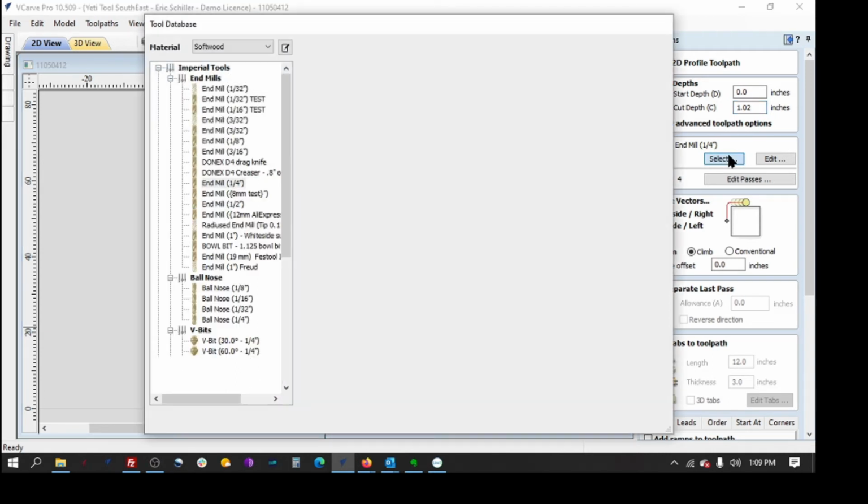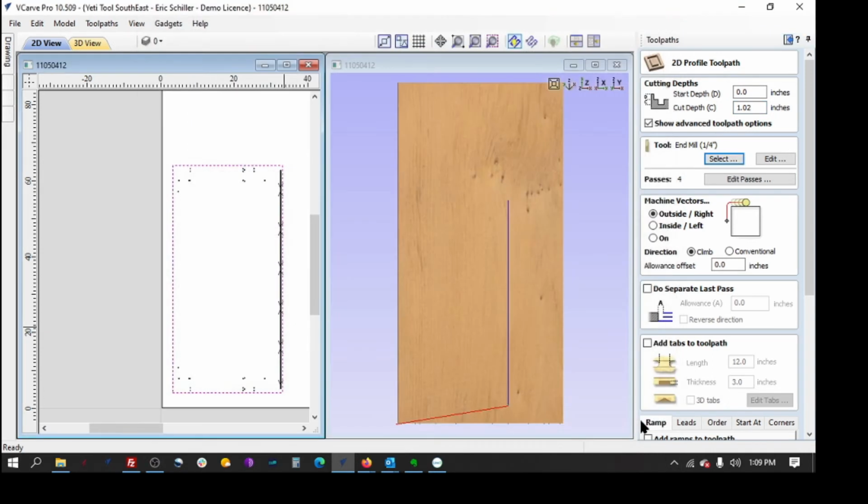I could do it still with the 1/8 inch tool, but that'd be a lot of passes. Depending on the production needs, I may want to go instead to a different tool and cut it at a faster speed. Because if I use a 1/4 inch spiral O, I can probably do the full diameter of the bit in each depth of cut, and I can do this in 4 passes. Plus, I'd probably do a finishing pass to take away the witness lines of each of the depth of cut changes.